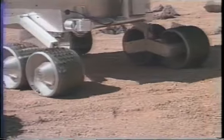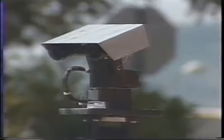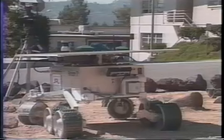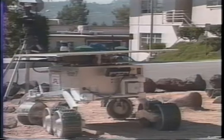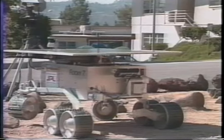When the rover arrives at a specified waypoint, an automated rover localization is performed. The rover tells the lander its approximate location, and the lander points its cameras at the rover and takes an image pair. The rover then makes a slight move, and another lander image pair is taken. The rover location is then computed using a differencing algorithm applied to the two image pairs. The rover automatically updates its position with this information.